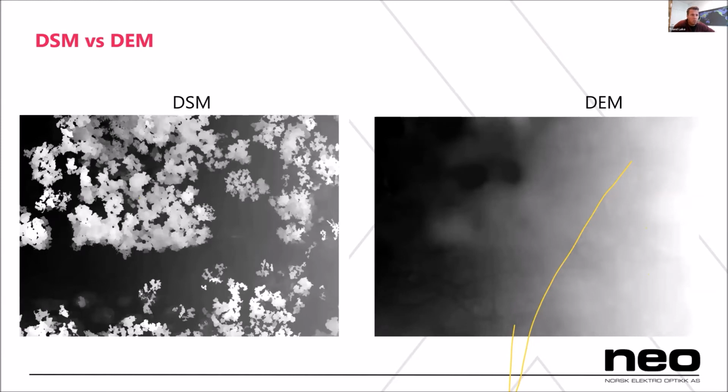So when should you use an elevation model and when should you use a surface model, right? An elevation model is basically, if you are processing a point cloud from a LiDAR and making an elevation model, the software you use, and there are many, is filtering out the trees, or everything that has high spatial frequencies. So you're basically generating the ground, not the surface model.